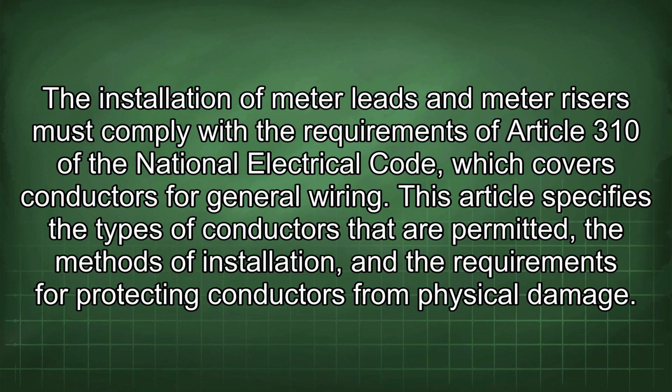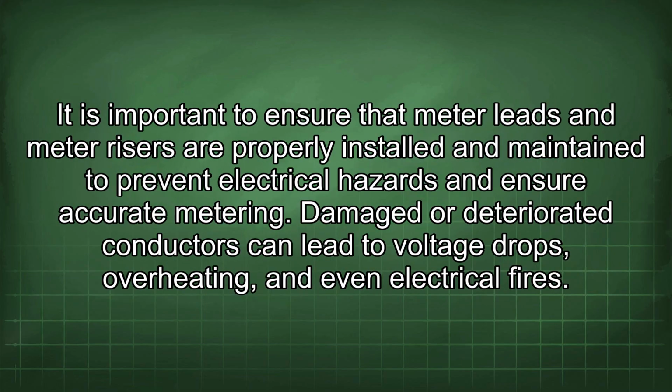This article specifies the types of conductors that are permitted, the methods of installation, and the requirements for protecting conductors from physical damage. It is important to ensure that meter leads and meter risers are properly installed and maintained to prevent electrical hazards and ensure accurate metering. Damaged or deteriorated conductors can lead to voltage drops, overheating, and even electrical fires.